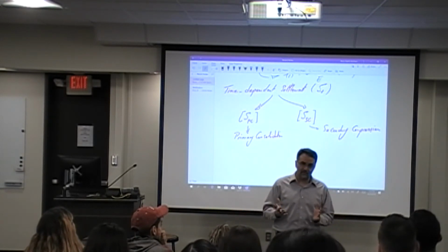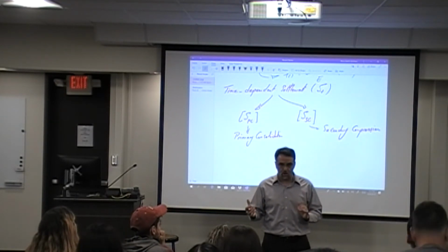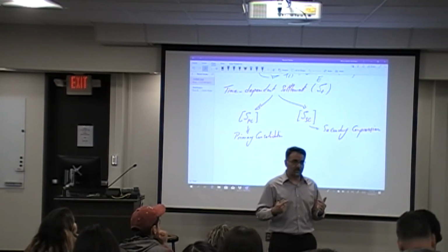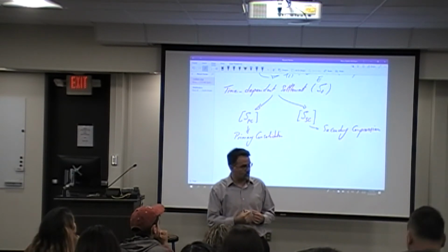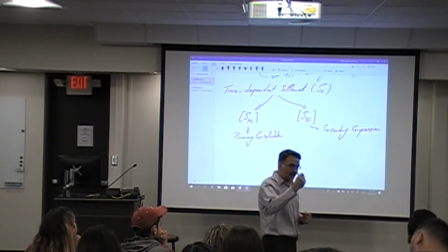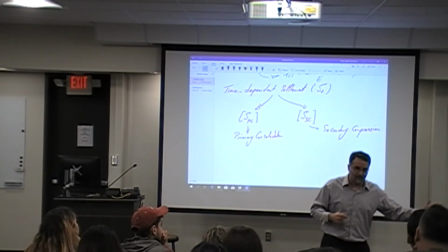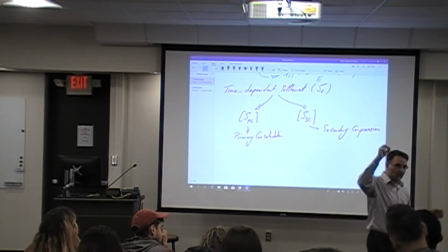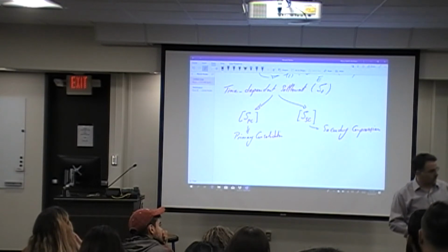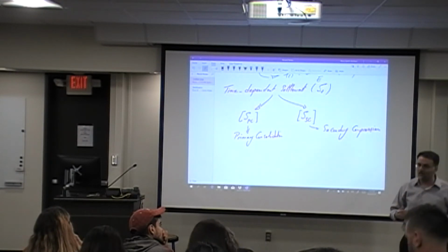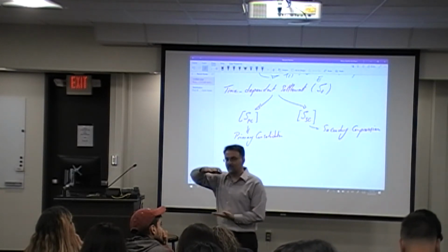So the permeability of the clay materials are high or low? Low, right? So this is the way that you have to think about it. Remember, permeability has to do with the speed of the water molecule that passes through the medium, right? So these nanotubes, the path of the traveling water molecule is going to be long. Therefore, it takes much longer for that water molecule to travel from the top of the layer to the bottom of the layer. Therefore, the permeability of the soil is going to be low in that case. Make sense?